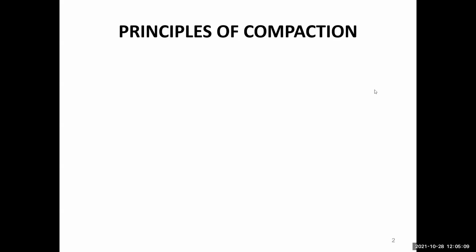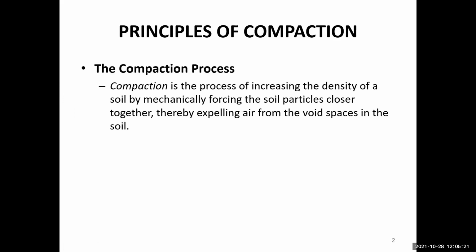So for understanding the compaction, first of all, let's understand the principles of compaction. The compaction process is the process of increasing the density of soil by mechanically forcing the soil particles closer together, thereby expelling air from the void spaces in the soil.